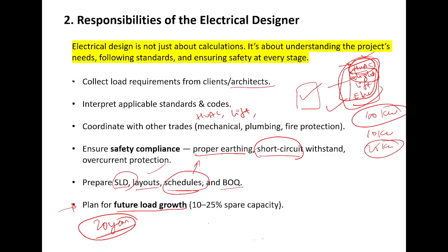So these are some basic and fundamental responsibilities of a design engineer. These are the fundamentals and will not change, but some may be added as per your client. So you should collect data from the client, comply with the standards and codes, coordinate with your other teams, ensure safety compliance, and prepare layouts, SLDs, schedules, and plan for future growth. I hope it is clear. Okay, please keep this in mind.